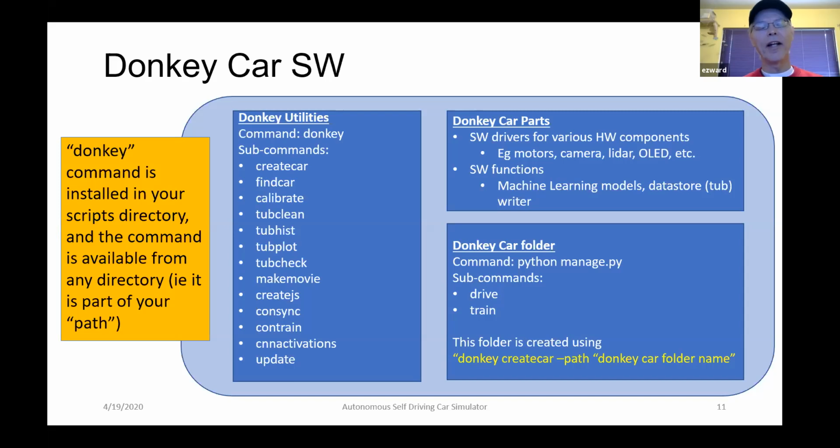Yeah, and a related thing is the necessity to have your configuration, your myconfig.py, be the same on both. So you create your calibrate on your Pi, and you end up with your myconfig.py on the Raspberry Pi or the Nano. And then before you train, along with your data, you should send your myconfig.py over to your PC, because those PWM values that you showed earlier need to be the same. The value that the autopilot is going to emit when it infers a throttle or steering depends on those values.